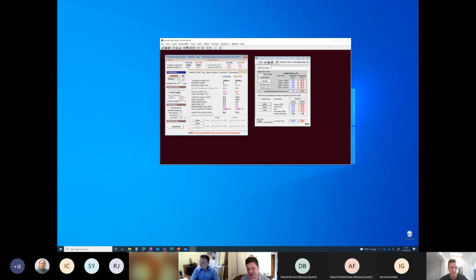So in GLD, this is where we put the loads in. Most of the time we're using monthly loads. So this would be a load summary that Mark Fontaine's team would have provided for us. And we put that load summary right into GLD. And that's a peak load and monthly kilowatt hours that's delivered. So it's a heating only system, 24 kilowatts peak, and it's delivering 78,127 kilowatt hours over the year.